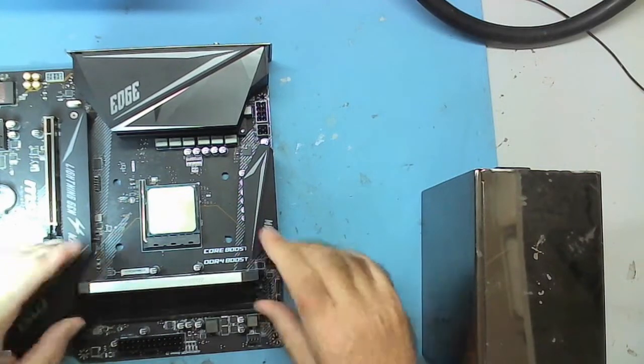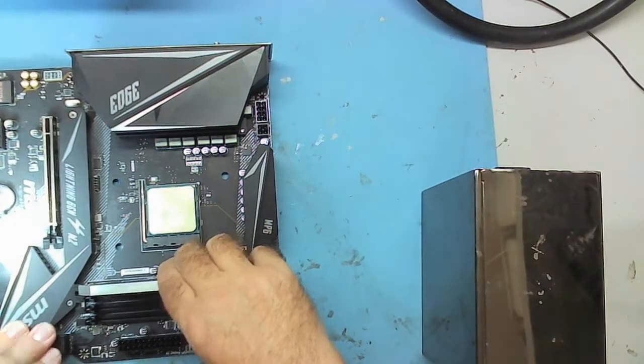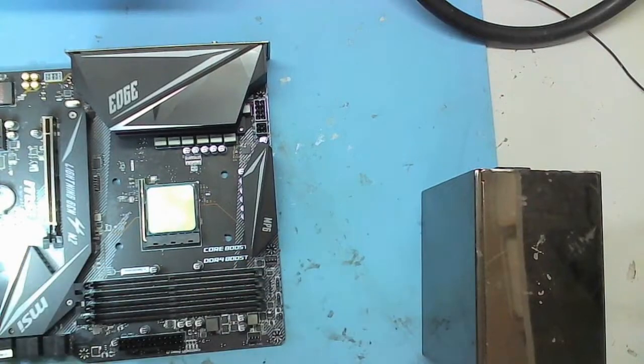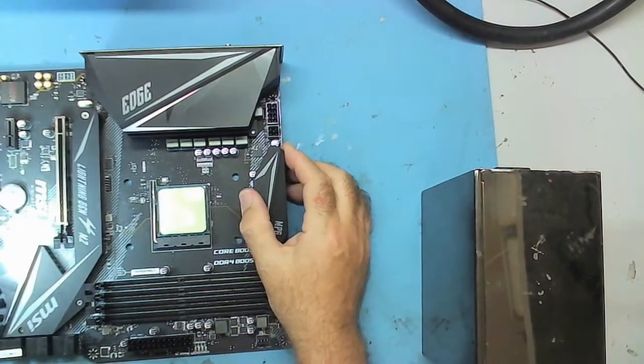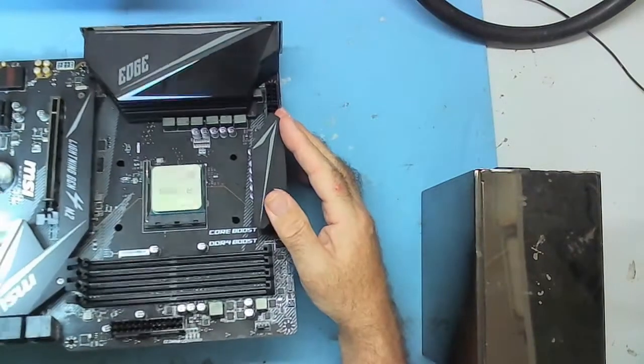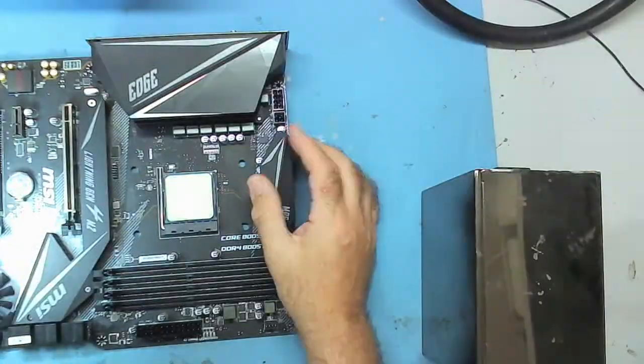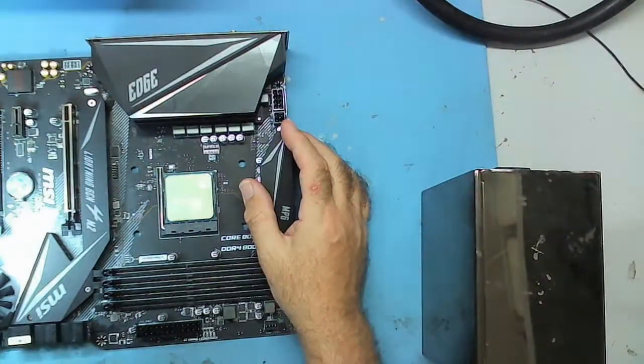Used, obviously. Yeah, which slots do they go in? That's a good question. In fact, no. Let's not even put them in. If we don't put the RAM in and power this up, it should bleep to say there's no RAM, and that's a very good sign that a board's actually booting. If it's booting and bleeping with no RAM, then fit the RAM. If it doesn't boot and bleep with no RAM, it probably isn't going to work anyway.